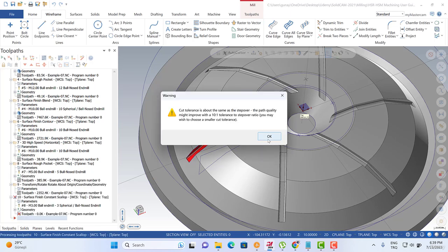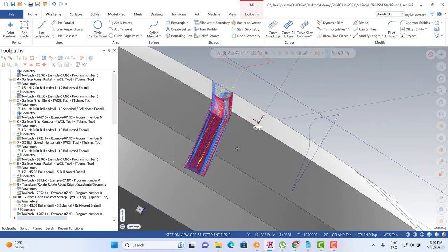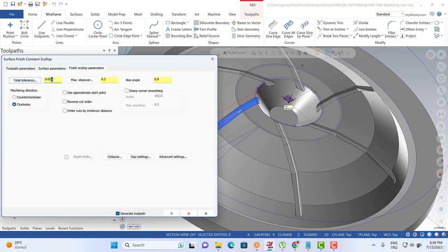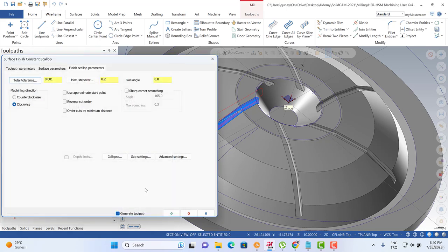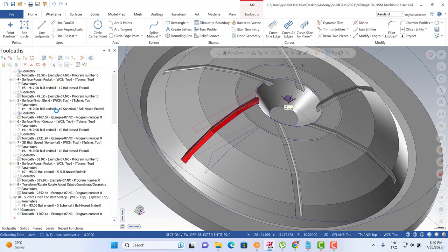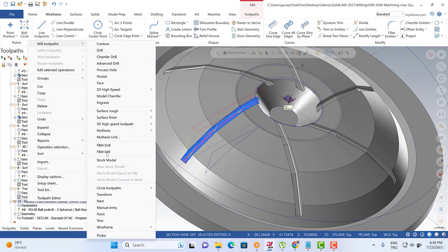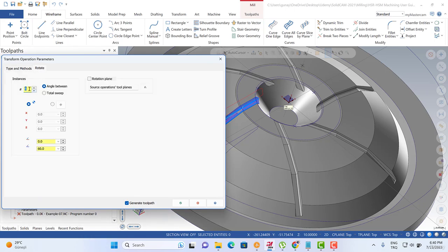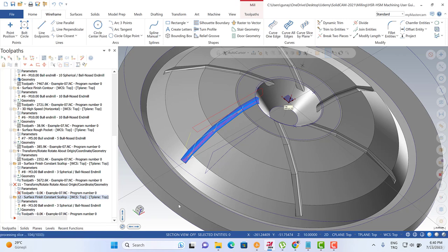After that, this is the tolerance approach actually. We can also change that, and then we can easily turn to the rotate options. Let me organize my tolerance like this one, and then we can recalculate our toolpath, and then we can use the right mouse button, Mill toolpath, and the Transform options. We can select this one and the rotate operation, 6 rotate operations starting from 0 to 60 degrees as an incremental, and then we can calculate it.